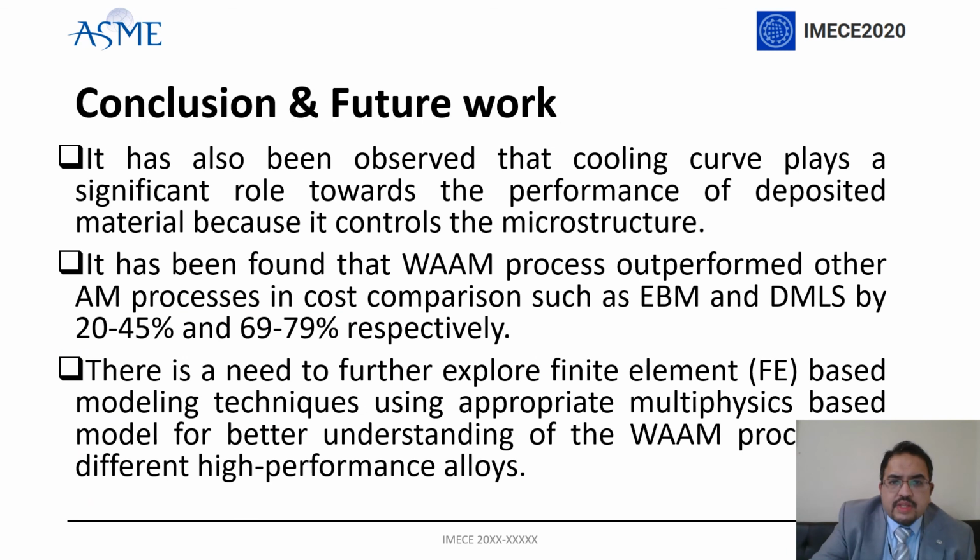In the end, some conclusions and some futuristic directions. It has been observed that the cooling curve plays an important role in the performance of the WAAM samples because it controls the microstructure. When the cost comparison is performed, the WAAM process outperformed other counter processes such as EBM and direct metal laser sintering by 20 to 45 and 69 to 79% respectively. There is again a need to further explore finite element based approaches where multi-physics models can be engaged and the WAAM process can be simulated.